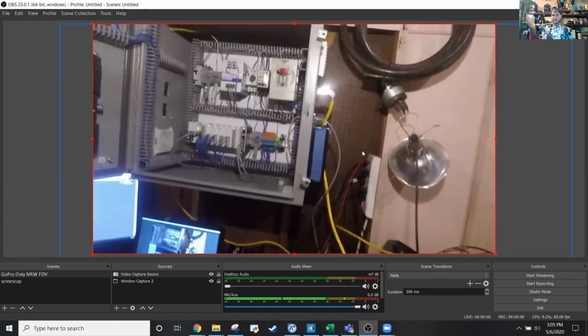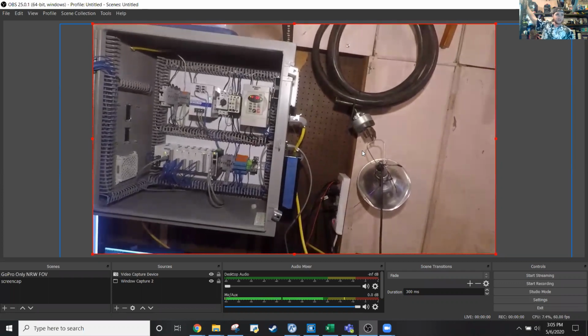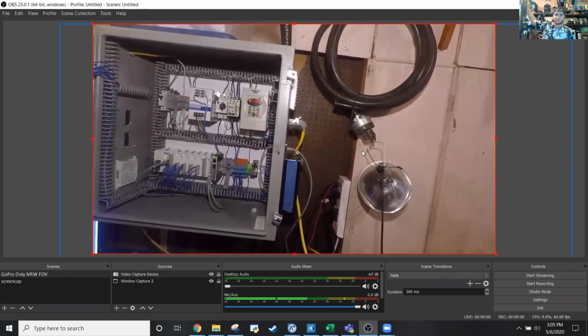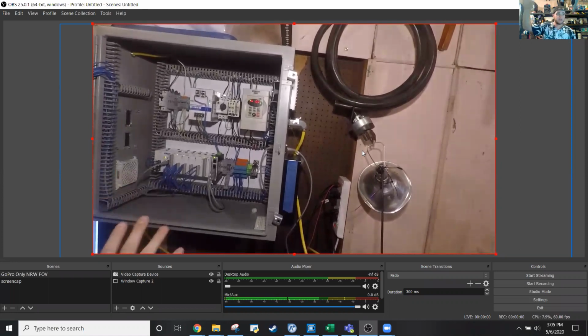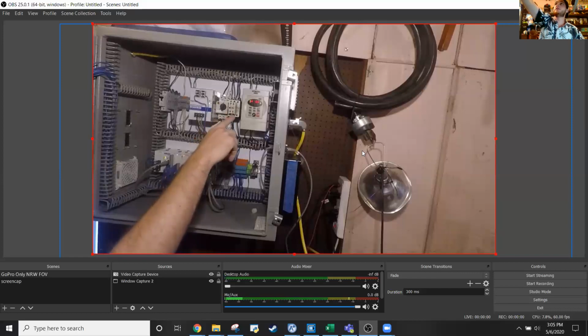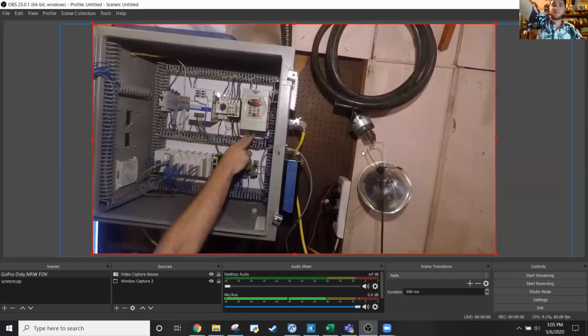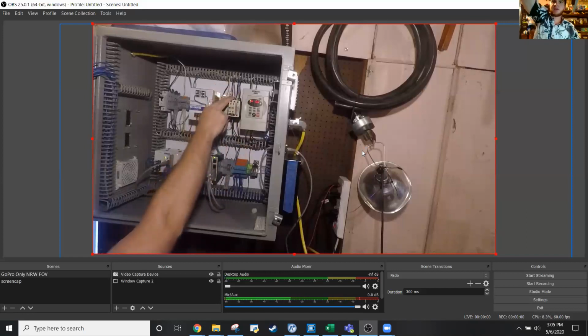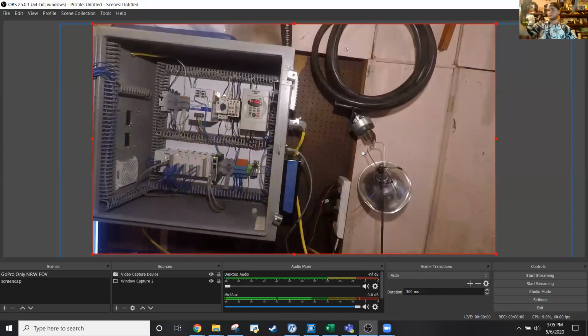I'm sorry I haven't done this yet. It's partly because I'm scared and partly because it's going to be super time consuming. I need to do a video where I do a build breakdown on this panel and explain what everything is and why it's all wired together, because I think it'll help y'all make sense of this stuff in your programming. But basically this right here is a motor contactor, and it's the wiring from the VFD. This is the output to the motor. This is wired into the top side here, and then it comes out the bottom and out the panel to the motor.